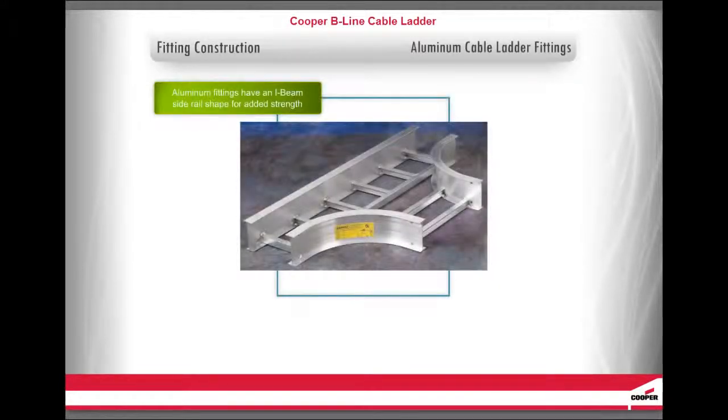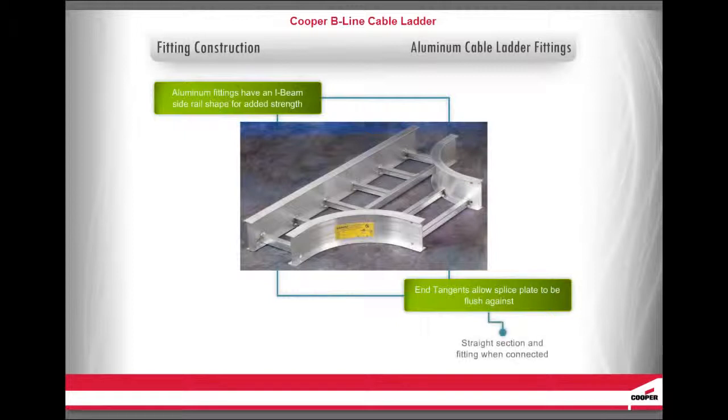The aluminum fittings have the I-beam side rail shape for added strength. End tangents allow the splice plate to be flush against both the straight section and the fitting when they are connected, increasing the contact surface area and the strength of the overall system.